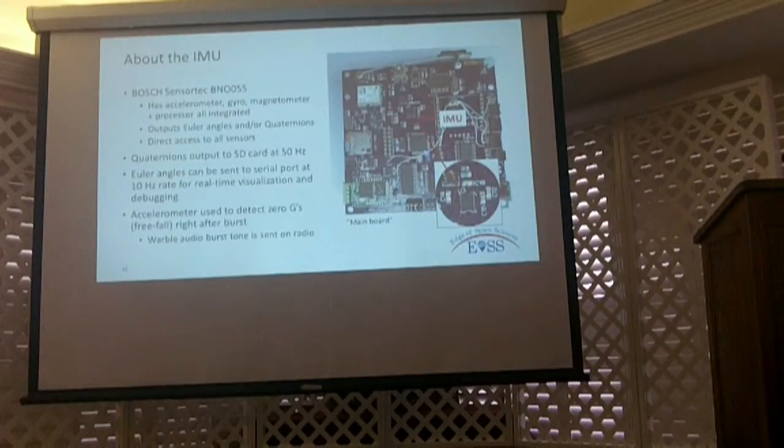The nice thing about this one is you can do a lot of this yourself. So you can buy a board that has the sensors on it, and then you can do the fusion algorithm yourself. And I started out doing that. You can start out by doing the math and the processor and all that. But for about $8, it's nice just to be able to have this one. You can also buy the breakout board for this from like Adafruit, so you don't have to try to solder this thing onto the board.